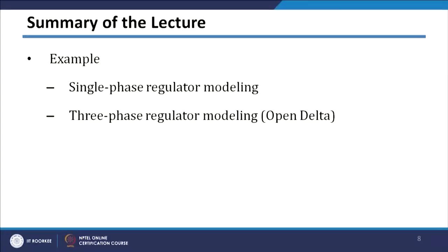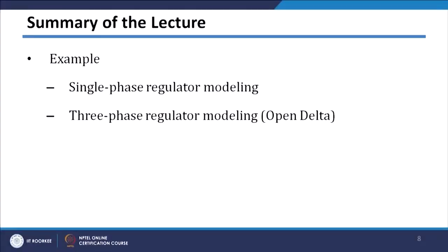In the summary of today's lecture, to understand the regulator better, we have taken two examples. One is on a single phase voltage regulator, where we calculated the settings so that the voltage at the feeder end is within the required bandwidth. Similarly, we have taken one example of three phase voltage regulator modeling, where we considered regulators connected in open delta fashion, and in this case also we calculated tap positions of those two voltage regulators which control voltage at the feeder end.